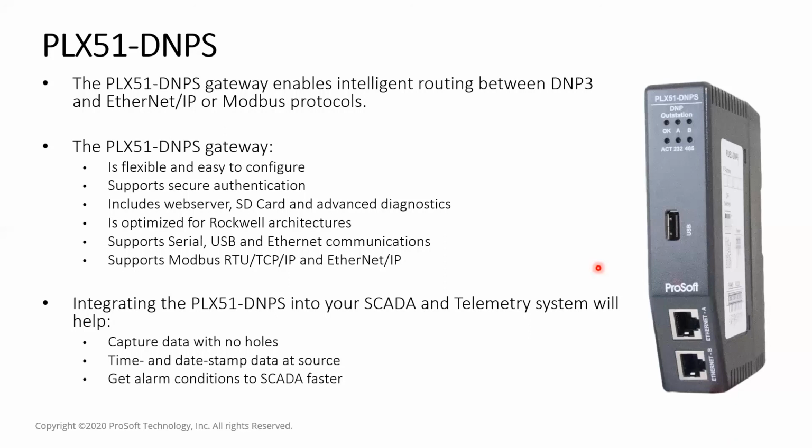So an unsolicited message is where the outstation recognizes that there is an issue, the pump has gone faulty, or the pressure is high, or the temperature is high. It then sees that the alarm condition is satisfied. It then initiates a message to the top end SCADA to say, I've got an alarm, you need to come and get the information.